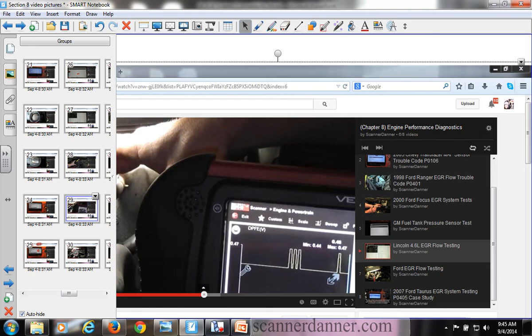Back up, I got the wrong vehicle. When I put my finger over this port, nothing changed. There was no rough idle. I apologize. The next one coming up, that's what it's going to be. There was no rough idle, no change whatsoever in EGR flow based on sound.